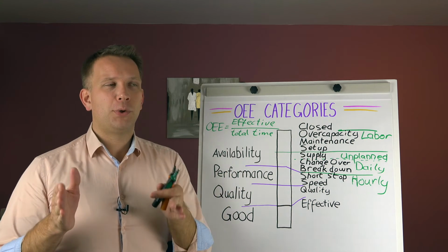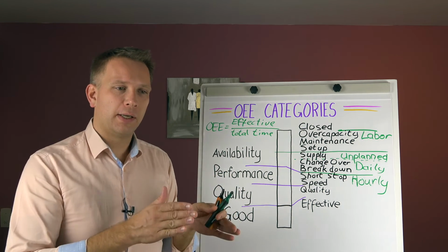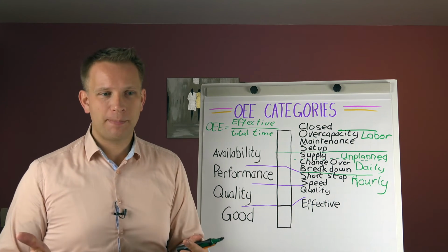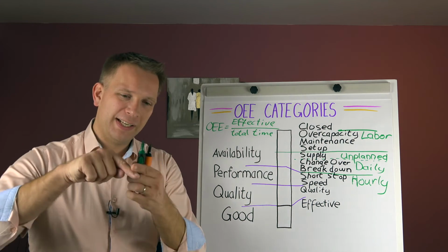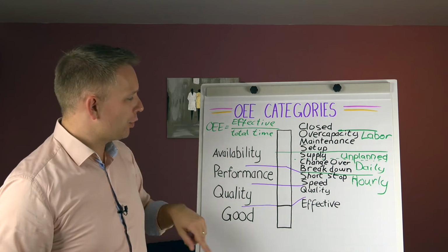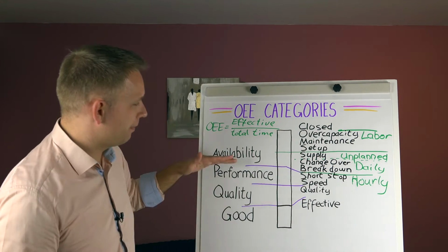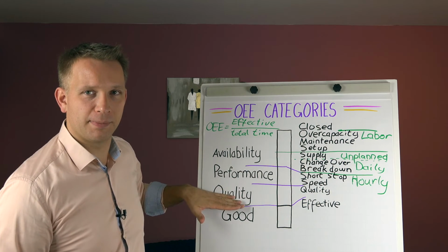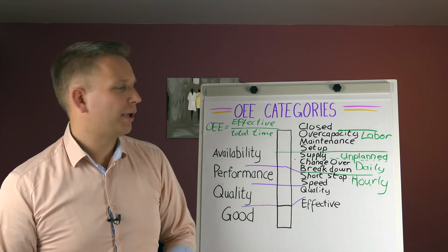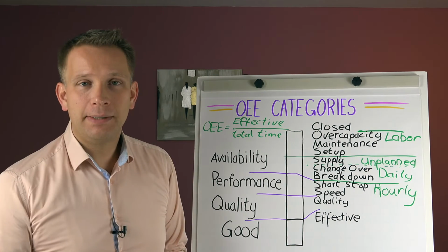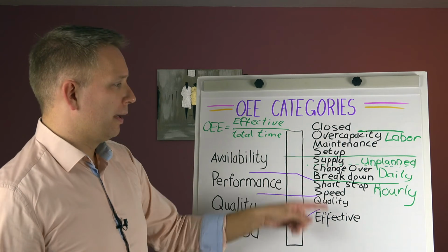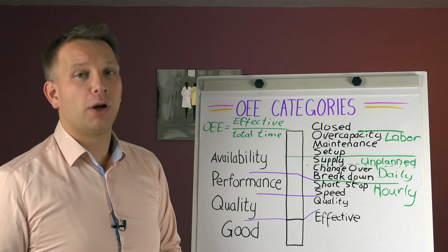But if you are checking how well your line has been running, if you, for instance, had a 20-minute changeover in the last hour, you also want to know about the other 40 minutes. How was I performing? On those 40 minutes, you want to know my performance and quality numbers. So that's why on that hourly line board, you want to keep them in. But daily, if I'm the production manager, so that's more of a daily scope, breakdowns and changeovers are really